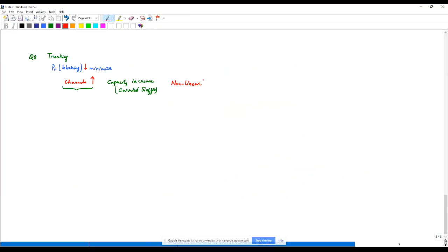Okay, so as you go to 100 channels, you'll see that the traffic carrying capacity is significantly high. So one of the key things that we always want to keep in mind is to have as many channels available for you to deploy your system, so that you can then get the advantages of trunking capacity. Okay, so trunking efficiency. That is the underlying principle. I'm assuming that that is the question that you are having.